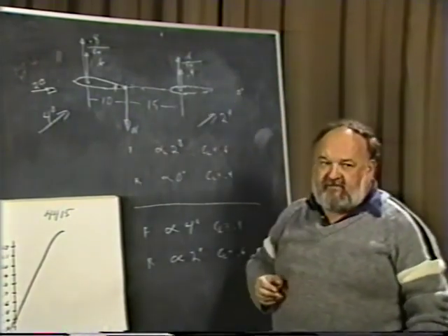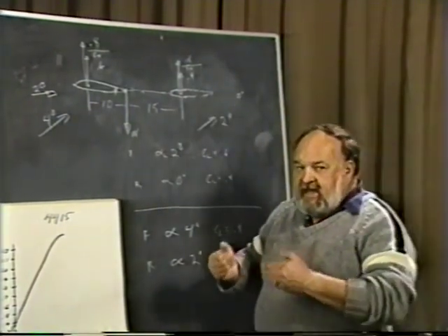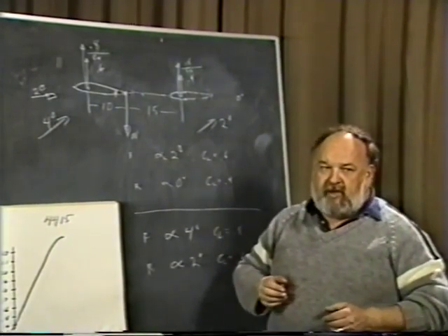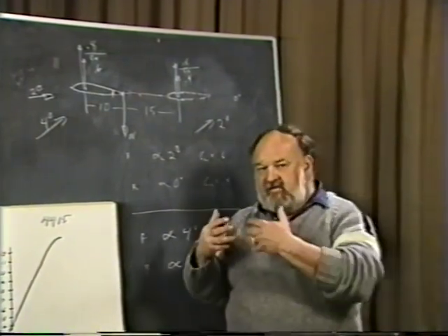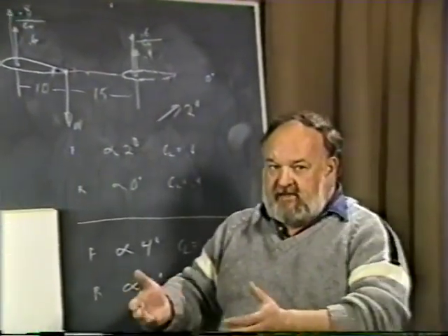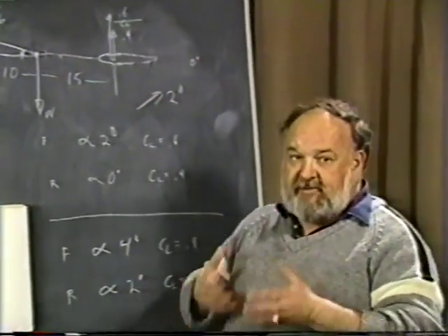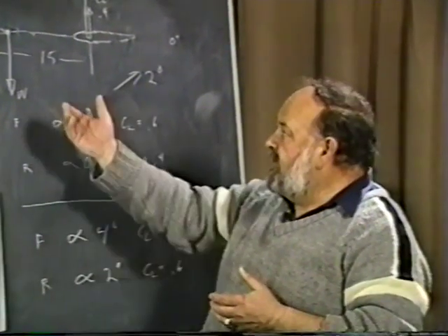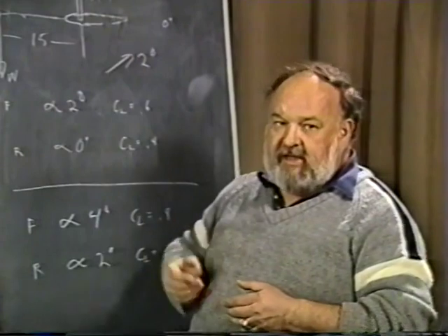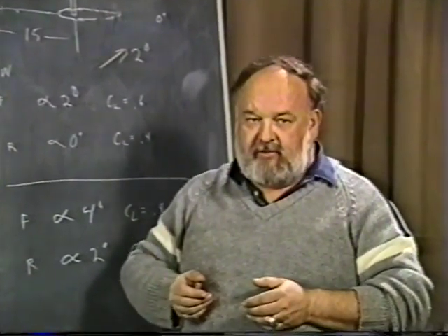even though it's a very, very big surface. Well, you can see, as you move it forward, you're making your tail become more and more powerful. That's why when a CG moves further forward on the airplane, it becomes more and more stable. As it moves further aft, the opposite starts to hold true, and eventually you can keep moving back to the point where you have neutral stability, even though the tail is of the same original size you had before.